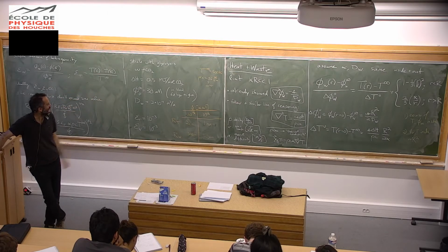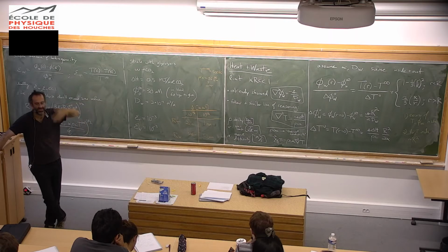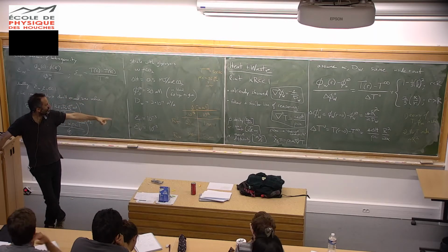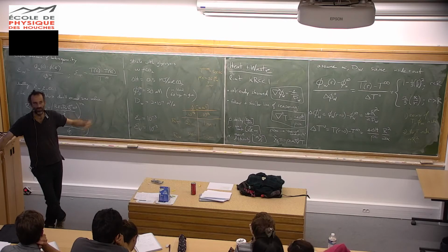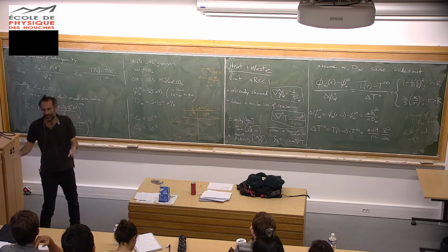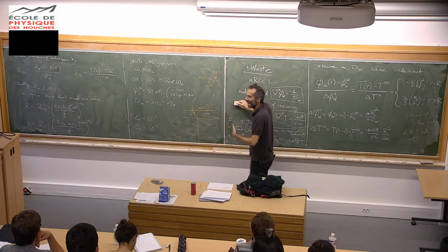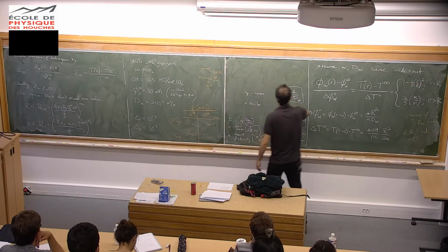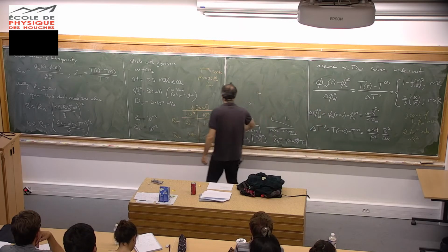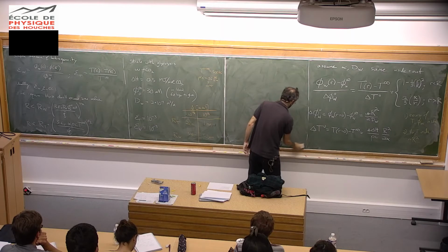In these experiments, and this is a point I'm about to make, I'm assuming everything's diffusion limited. If I convect on the outside, I can improve these numbers a little bit, but not a lot. What you really need to do to get these numbers a lot smaller is to have internal convection, which is a lot harder from an experimental standpoint. But to answer your original question, I don't know. Certainly the people that do heat transfer talk about the boundary layer thickness. So that's the bulk of the calculation that I wanted to do today.